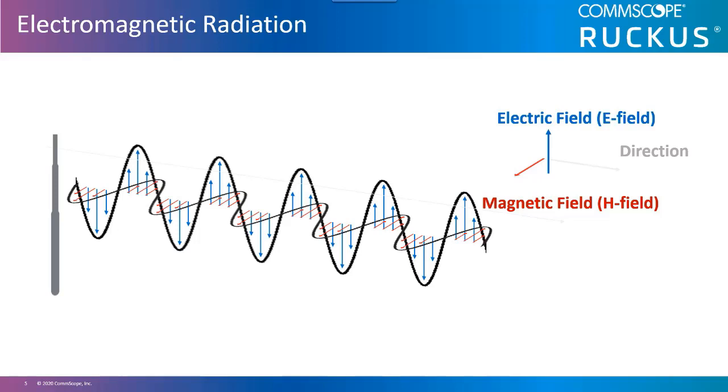The E field creates an H field and vice versa. These two fields create a continuous pattern. This pattern moves the electromagnetic radiation through space. Knowing the basics of propagation is important. You may see antenna chart patterns referencing E field or E plane as well as H field or H plane. These charts give engineers a visual representation of the RF wave patterns each antenna provides.